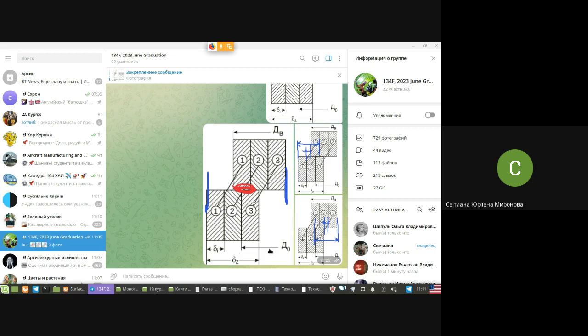And this employee just takes parts one by one from the box and assesses whether each is in the range this gauge provides or not. And due to this, you may, not you, but your employee, select parts into some subgroups. And the same for another assembly component, which is supposed to be assembled with these parts.